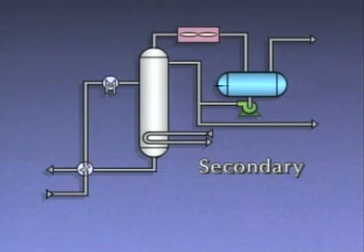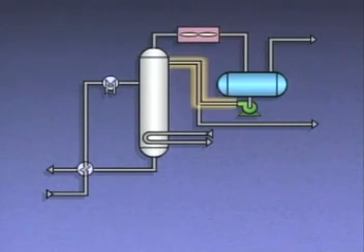Secondary energy flows are associated with heat transfer in which the heat remains within the distillation system. For example, reflux transfers heat out of some of the vapors in the column and condenses the heavier components. However, that heat transfer is between two fluids within the distillation tower. It doesn't involve an external medium, such as air or cooling water. The amount of secondary energy flow is determined by the external reflux flow rate.